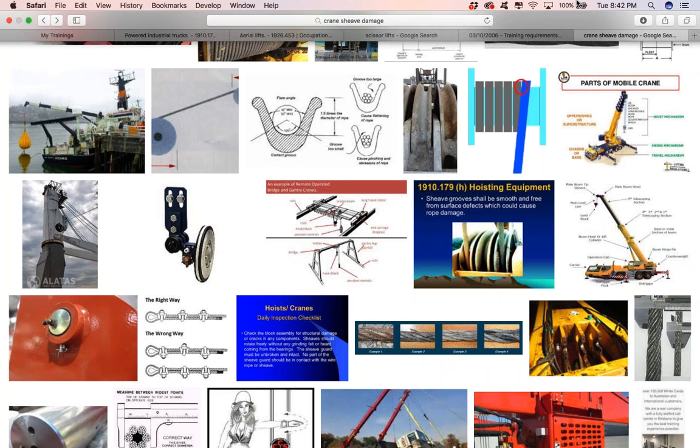But things we want to do is make sure that we drive slowly and never speed. We also want to respect the speed limit of that equipment. Know the distance it takes to stop safely. Allow extra time to enter traffic. That's why we should be using an escort, folks. Know and follow the traffic control pattern. Travel with the lights on. Use proper warnings and flags, secure all attachments and loose gear.